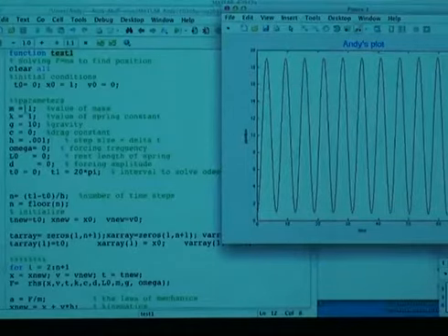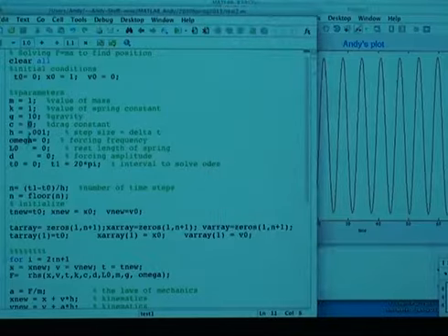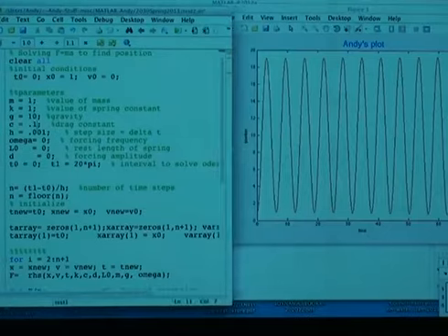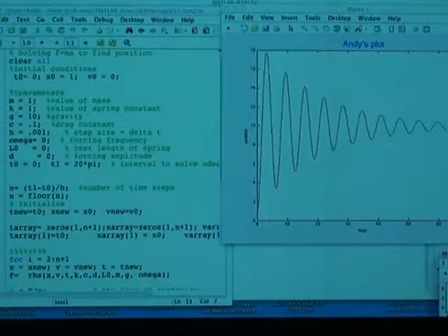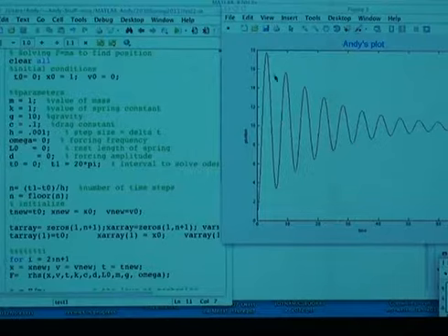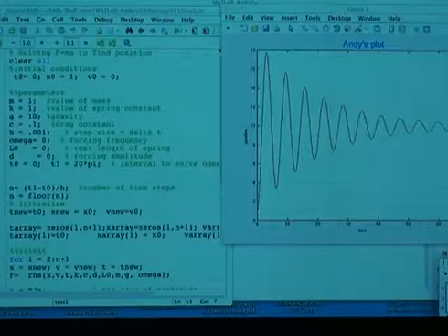Now let's add some features to this motion. Like let's put in a little damping. If I put in a little damping of 0.1, what's going to be the motion? Well, the way I've set the constants here, this is just getting the homogeneous solution. The homogeneous solution from differential equations is an exponential multiplied by a sine wave, and there's your exponential multiplied by a sine wave. Notice there's no exponentials or sine waves in this code at all. This is just what the numbers make happen.